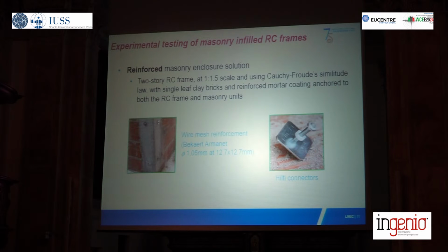So in this particular specimen, or not that one, a similar specimen, we were doing some reinforcement using a wire mesh reinforcement in a reinforced mortar coating, which was anchored to the reinforced concrete elements and also to the masonry units.